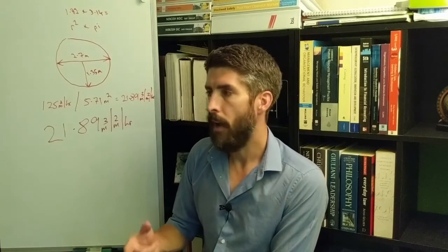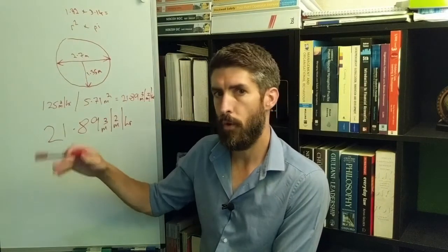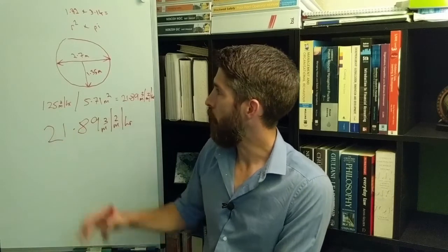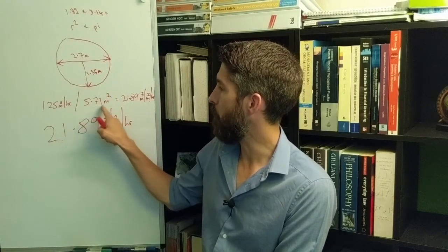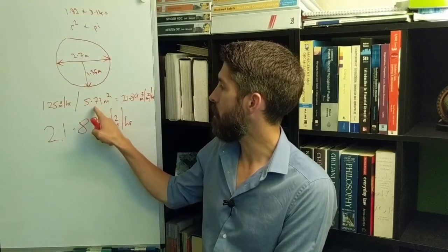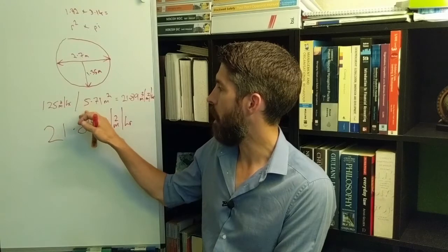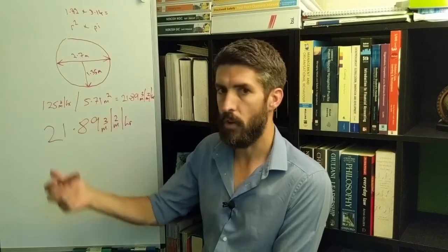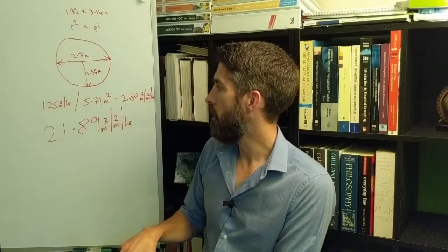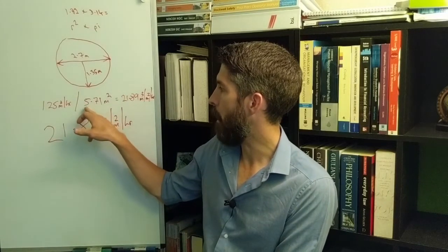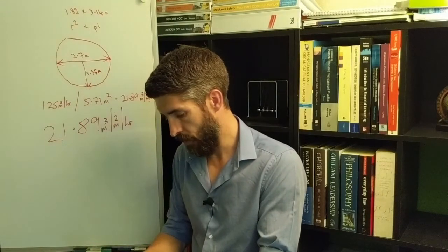One thing to add is, if you've got 2 filters or 3 filters, once you've worked out the surface area of one filter, 5.71, if all of your filters are 5.71 and you've got 2 filters, you'd have to double up that 5.71.